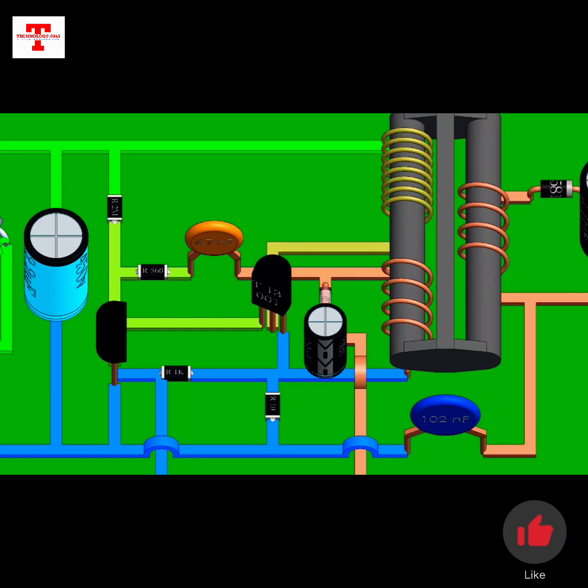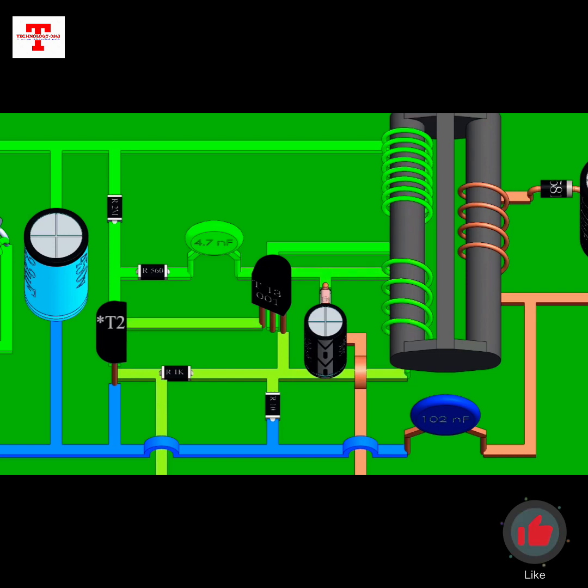Now, this current passes through the 2 megaohm resistor to the base of T1, turning it on. This transistor isn't fully turned on because of the resistance; it turns on partially. Due to the partial turning on of the transistor, a low current passes through the primary winding of the transformer. This induces a low voltage in the auxiliary winding. The induced voltage now charges the capacitor, and then the capacitor fully turns on the transistor. As the transistor is now fully on, it allows the current to flow through itself. Now, this turns on the transistor T2.